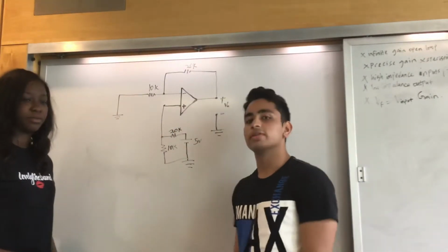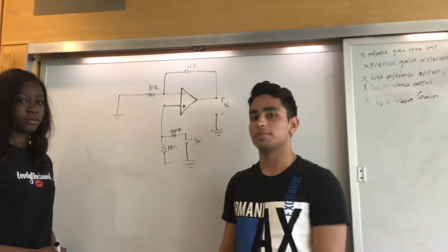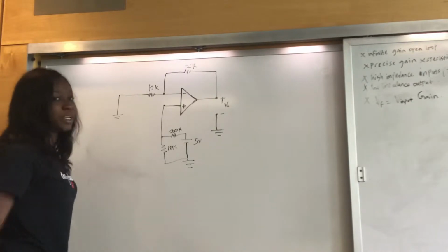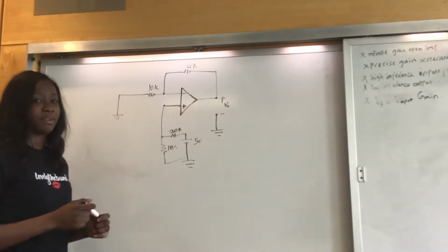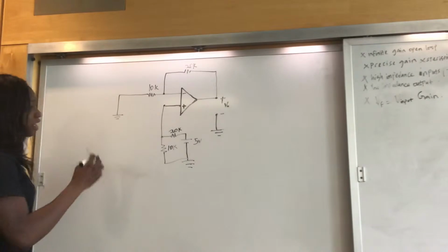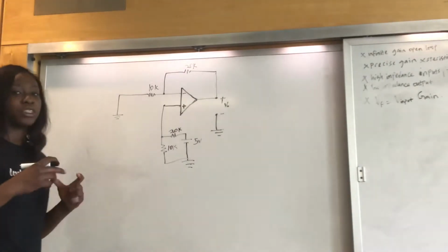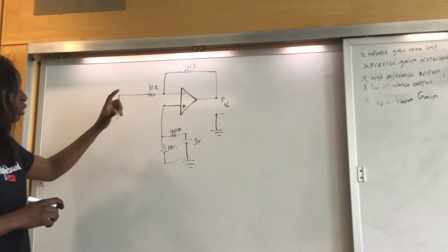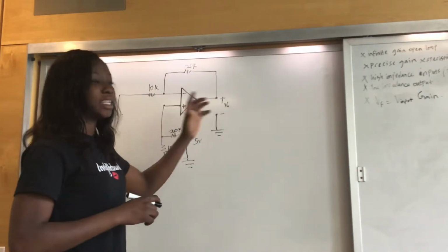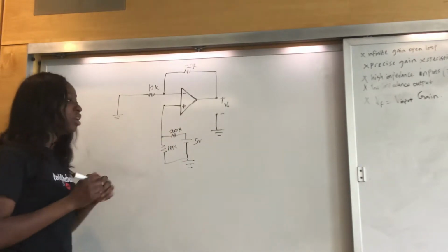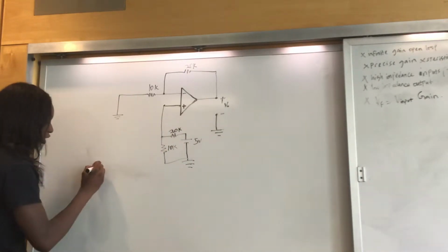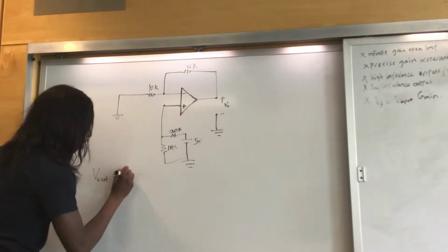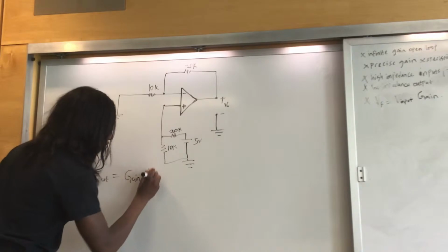And today we're going to be solving this problem and studying the basics of operational amplifiers. Before we solve this problem, it is important to understand what operational amplifiers do. What operational amplifiers do is they take an input voltage across two terminals, a negative and a positive terminal, the potential difference across those two inputs, and create an output that is a multiple of the input value. So usually what operational amplifiers do is there's a V out that is a gain factor of a V in.